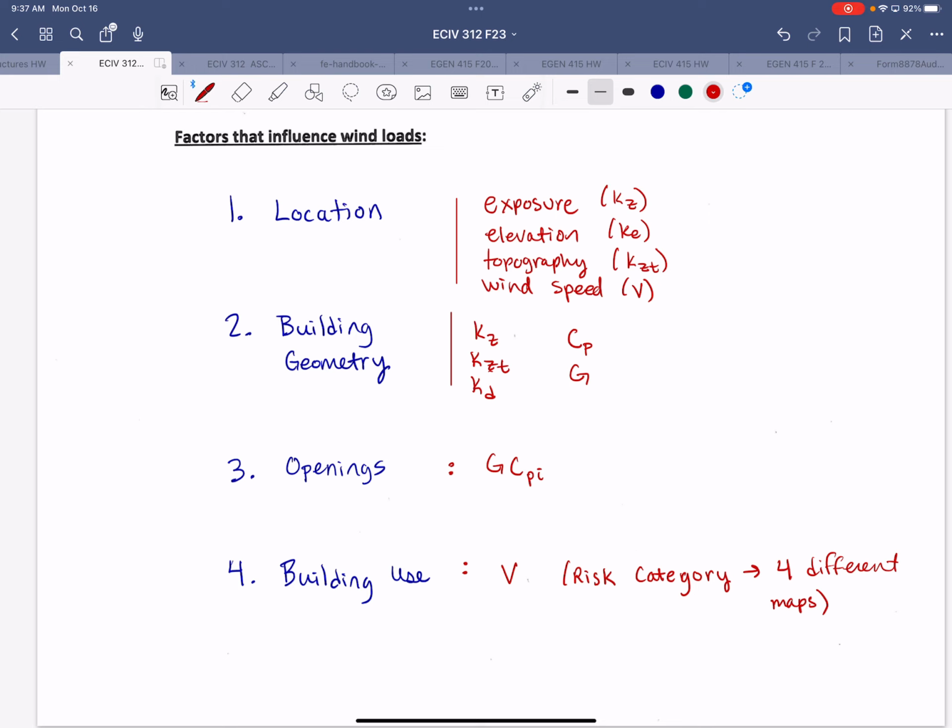So after the mid-1990s, any new construction should have those requirements met. But if you're ever in the market for a house and it was built before the mid-1990s, you just might want to verify that it's properly tied down and tied together to resist against uplift. So anyway, a little bit of interesting history for you there.